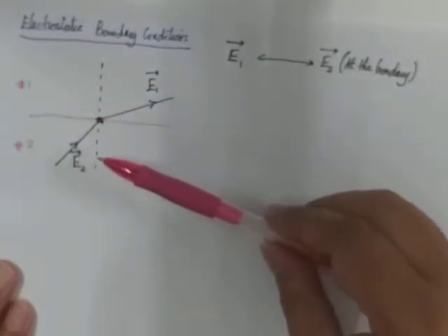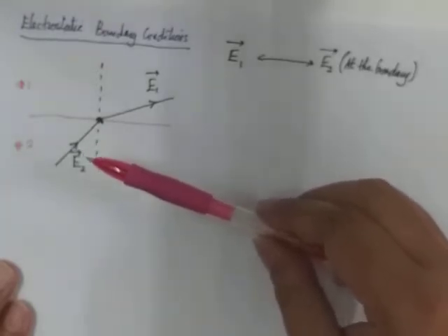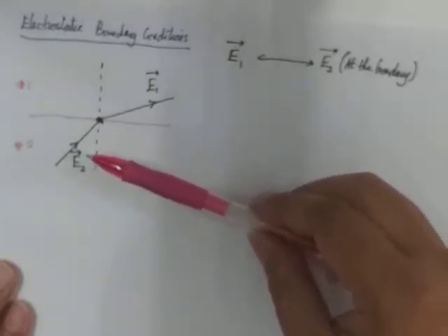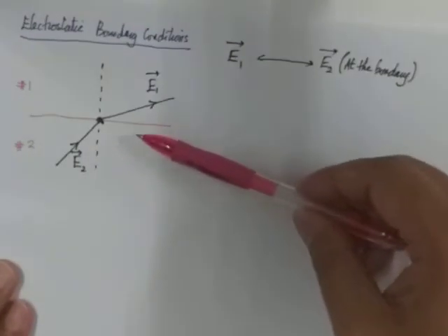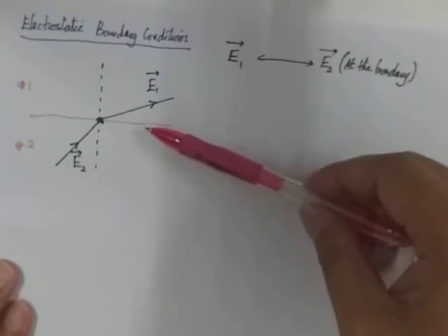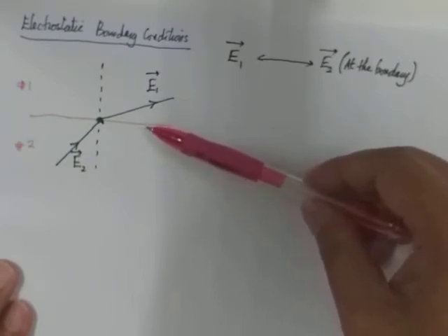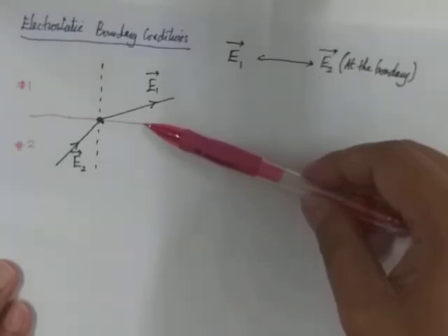So what we need to do in order to simplify the process of developing this equation is to see there are two conditions always constant with respect to the boundary. Regardless of what happens to the boundary, the normal component is always normal to the boundary, correct? Normal meaning the angle that field makes to the boundary always remains 90 degrees.